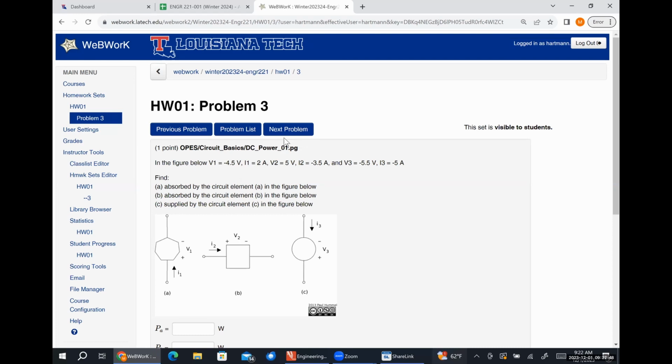That's all this takes. It's annoying for sure to have to do this all the time, but that's literally all the passive sign convention does. Look at which polarity terminal the current is flowing into, and then figure out, based on the quantity that you're trying to solve for, whether or not you need to add a negative sign. If you can do that consistently, you're done. Passive sign convention is great. Congratulations on probably an A in the class.